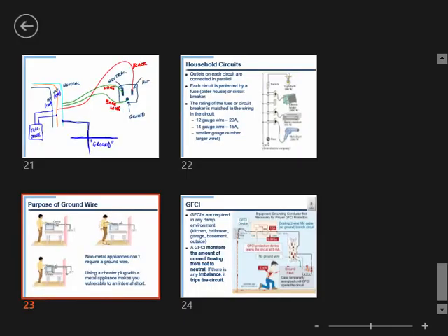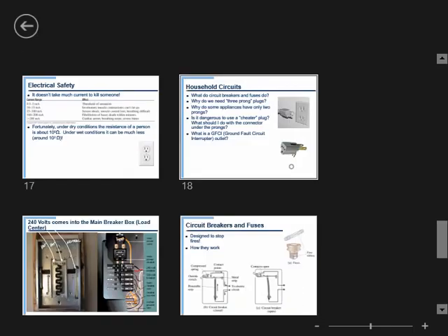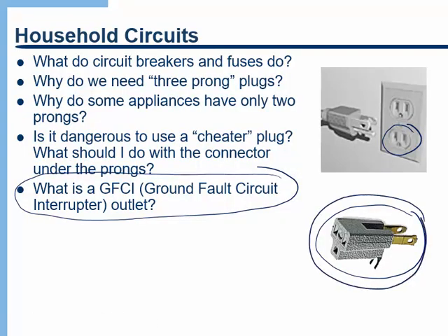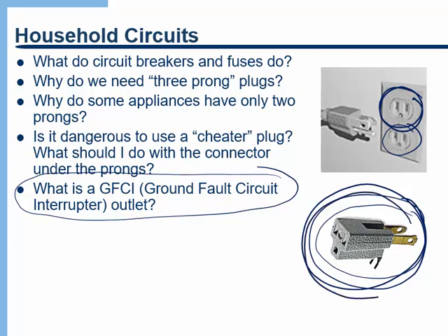Now, those cheater plugs that take a three-prong plug and switch it into a two-prong, again, just to make sure you know what I'm talking about, one of these. So if you have an older house, sometimes you'll have outlets that are only two prongs. Generally, these are not a good idea because effectively you're taking away the safety feature. And you really probably want to get an electrician to look at that and see if you can upgrade those two-prong outlets to three-prong.